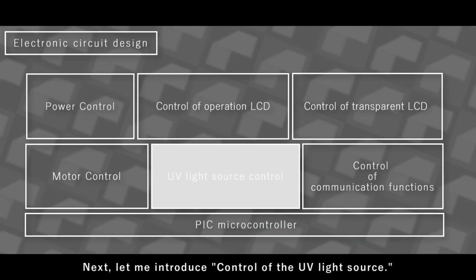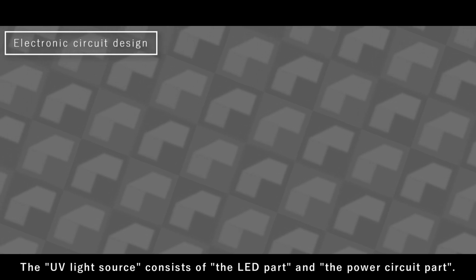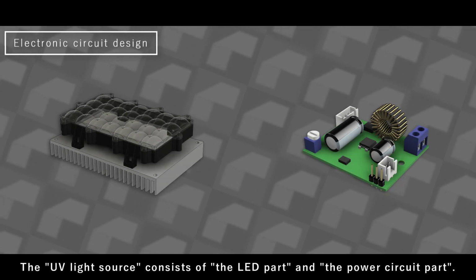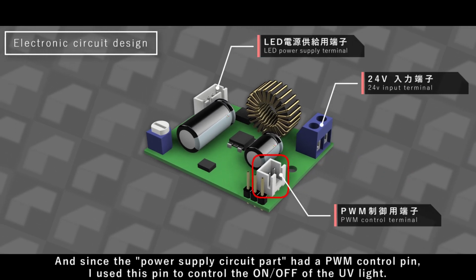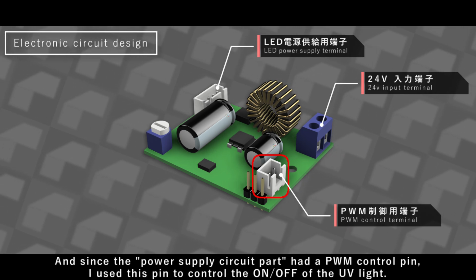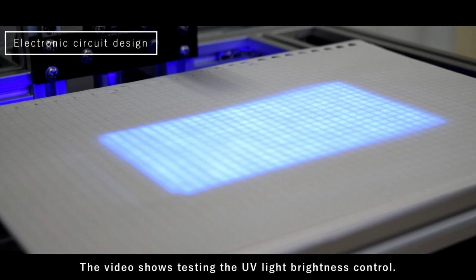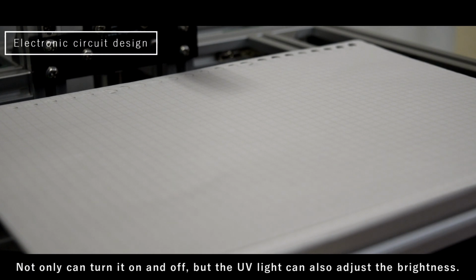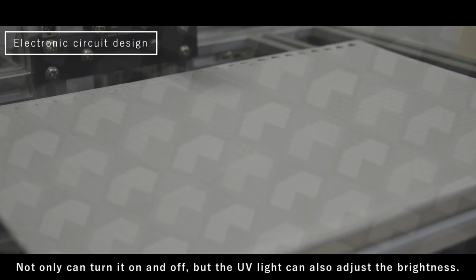Next, let me introduce control of the UV light source. The UV light source consists of the LED part and the power circuit part. And since the power supply circuit part had a PWM control pin, I used this pin to control the on or off of the UV light. The video shows testing the UV light brightness control. Not only can it be turned on and off, but the UV light can also adjust the brightness.